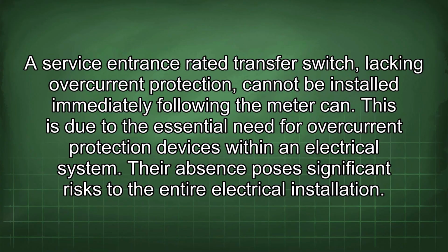A service entrance rated transfer switch, lacking overcurrent protection, cannot be installed immediately following the meter can. This is due to the essential need for overcurrent protection devices within an electrical system. Their absence poses significant risks to the entire electrical installation.